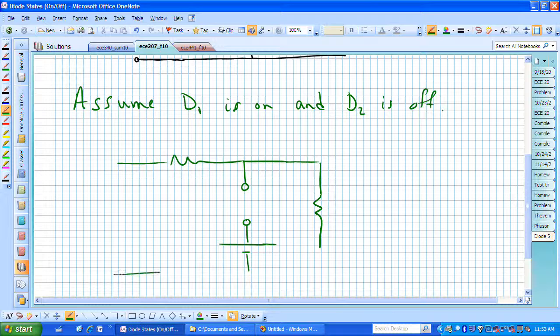It's going to now act like a wire with an ideal diode assumption. This was 1K, here was 1K, and here is our input source Vn, which we are allowing to be in some range, positive or negative, or bigger than 10, less than 10, something. And there's our 5-volt source.